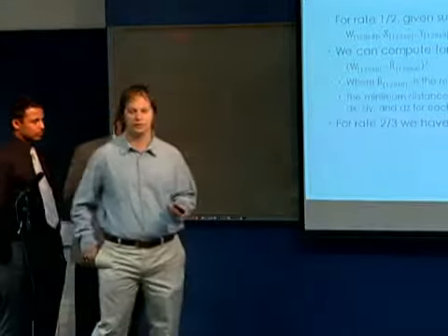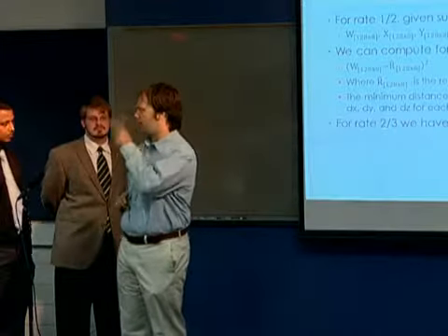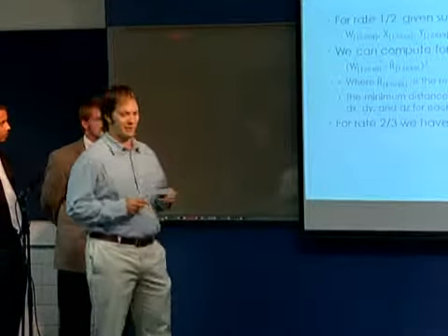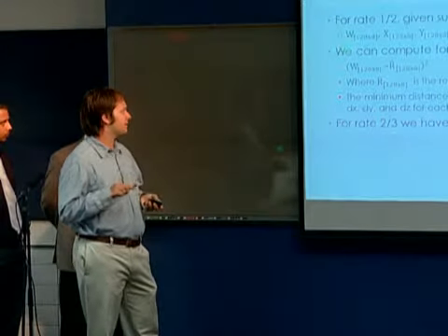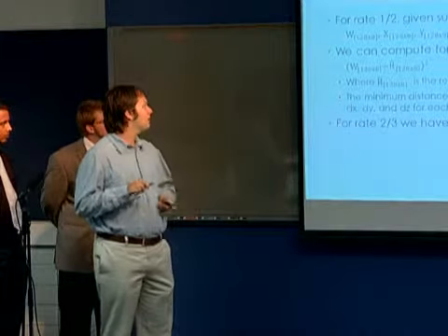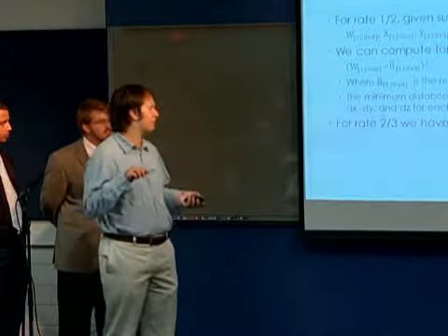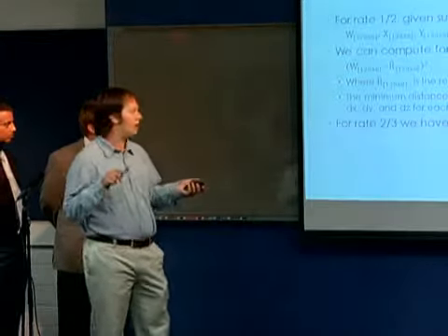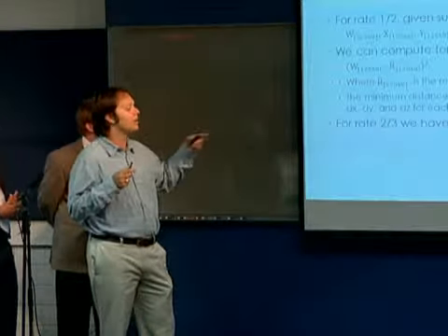Okay, so my part was to take everything that he did and just do it backwards, because we have to decode it. We know the subsets, and we are going to have those on the decoder side. So we take each subset, take the received signal, copy it a bunch of times, and do this calculation, just Euclidean distance, and then sum up. And we have then a list for each subset.